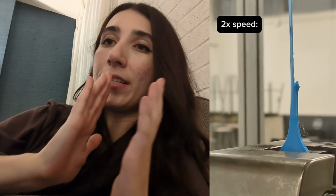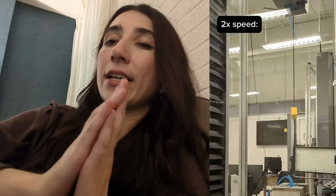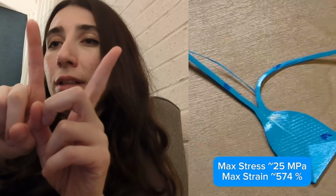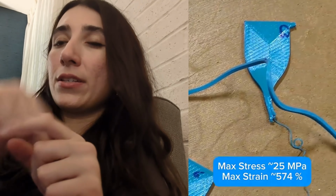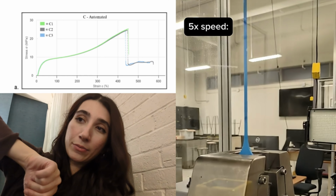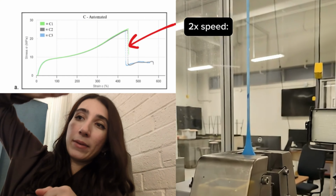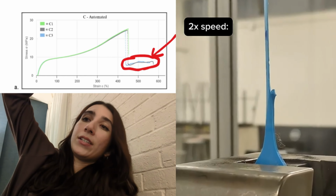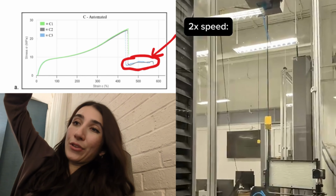What I observed in these samples while tensile testing at 500mm per minute, as the part stretches, the center starts to delaminate at the gauge length region, so now I'm essentially pulling 2 separate lengths. You can see how it looks like the tensile samples have 2 legs and how one of the legs is longer. What was observed was that the center of the gauge length delaminates, one of the halves rips off, and then the tensile test continues with the other half of the gauge length.